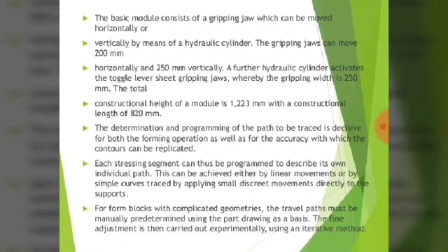The determination and programming of the path to be traced is decisive for both the forming operation as well as for the accuracy with which the contours can be replicated. Each stressing segment thus can be programmed to describe its own individual path.